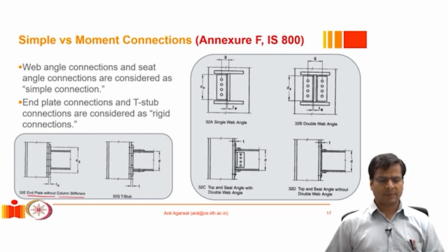And sometimes, in spite of this, you might realize that the flange itself, or this local area of the column itself, is not rigid enough to carry or resist the force demand that is coming from the flange. So one way to address that problem is to increase the thickness of the end plate, and sometimes still that may not be enough, and we may have to provide stiffeners in the column. Both of them are acceptable approaches.